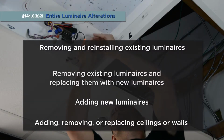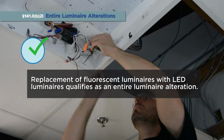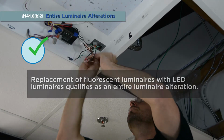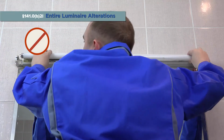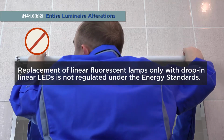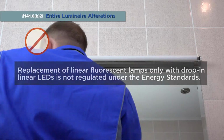An example of a project that falls under this category is an office building in which each fluorescent troffer is being replaced with an LED troffer. Alternatively, an example of a project that would not be regulated under this category would be removing just the standard fluorescent lamps in the troffer and replacing them with a linear LED lamp alternative.